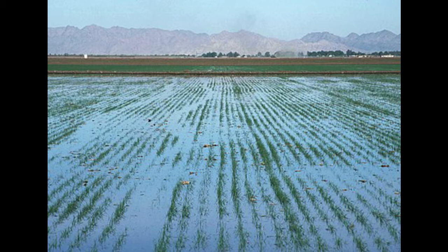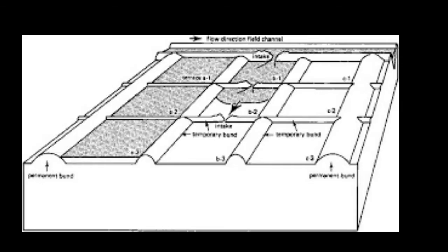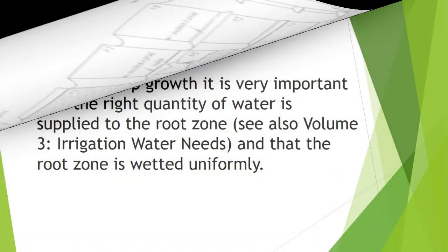When long cascades are used for growing rice, it is common practice to allow water to flow continuously into the terraces at low discharge rates. The water demand in the cascade can easily be monitored by observing the drainage flow. If there is no drainage, then more water may be required at the top of the cascade. If there is a drainage flow, then it is possible to reduce the inflow.